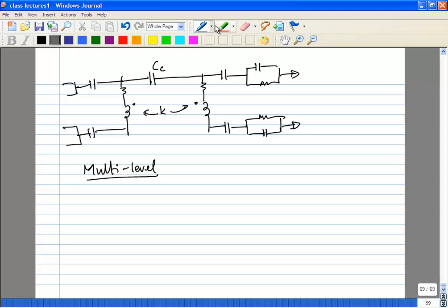There are cases where you do want that, where you don't care about the Q because it's already a very broadband circuit, or the inductor is already so de-Q'd that you're not using it as a resonant circuit. You may be using it in a different way.